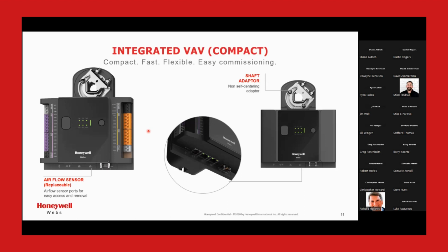And one takeaway of the older Spyder 5 controllers is they had way more memory, way more capability than a Spyder-classic, but they did not do anything over IP. They were strictly and are strictly BACnet MSTP controllers. So the Spyder 5 VAV, the Spyder 5 unitary, strictly BACnet MSTP.